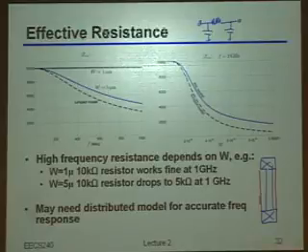So what does this say about how you'd like to build your resistors? How should you choose this width, especially if you're interested in the high frequency performance of that resistor? Skinny. Yeah, you want to make it as skinny as you can. Now, what sometimes stops you from doing that? Yeah, okay, the current capacity.